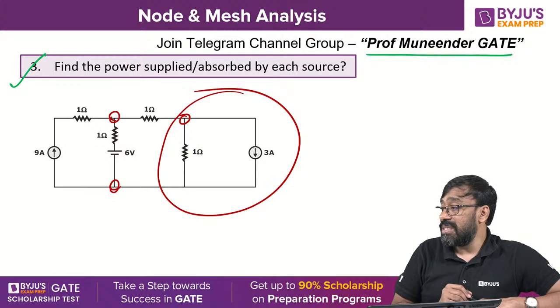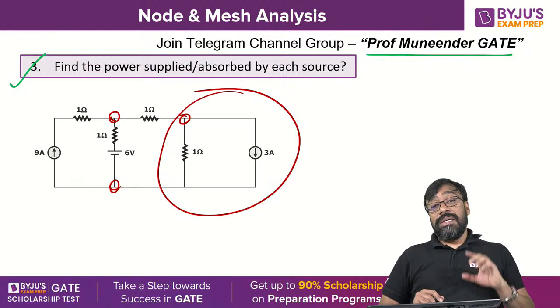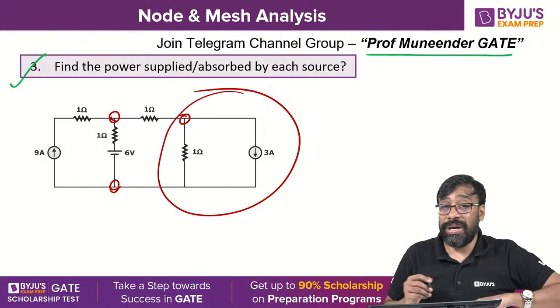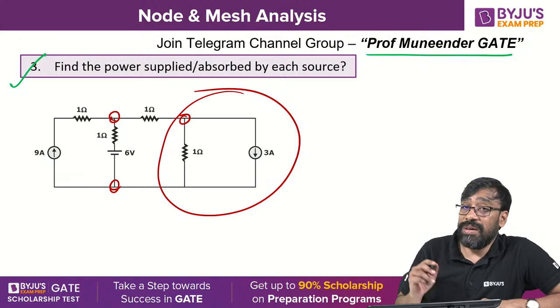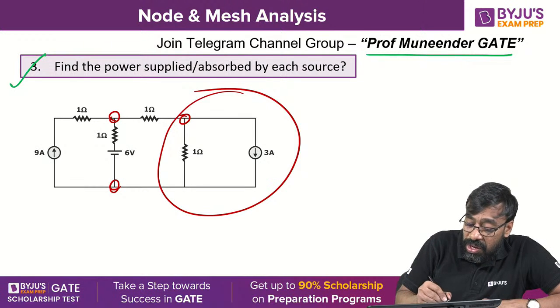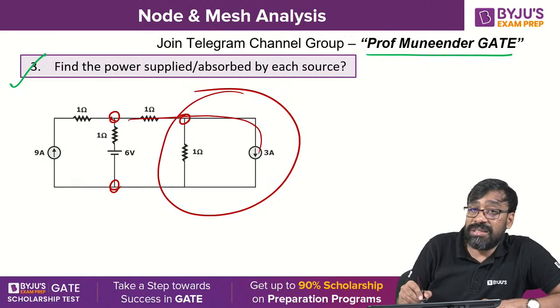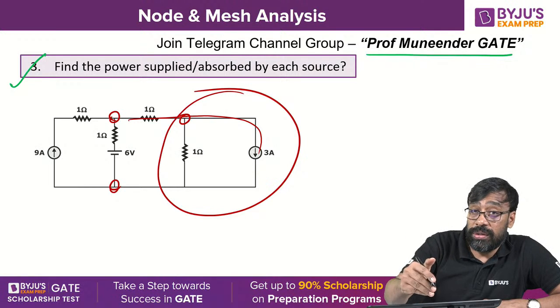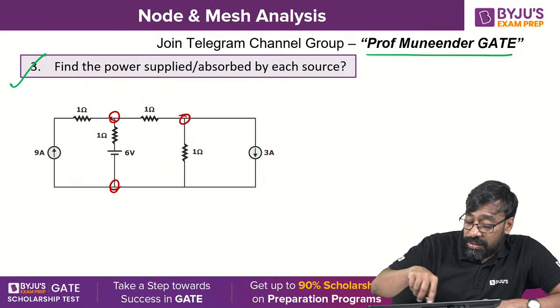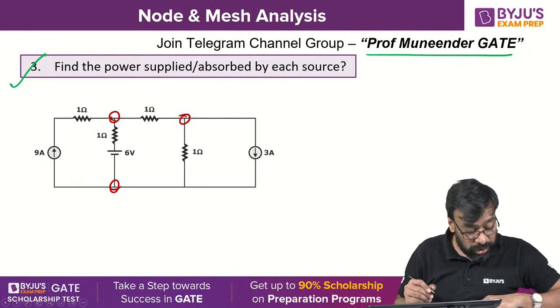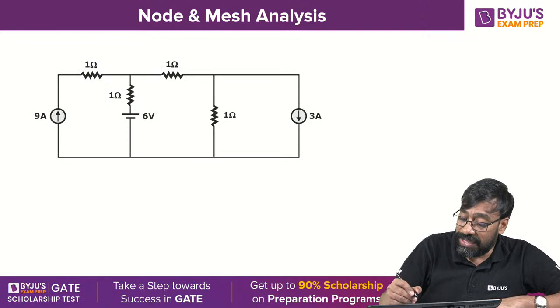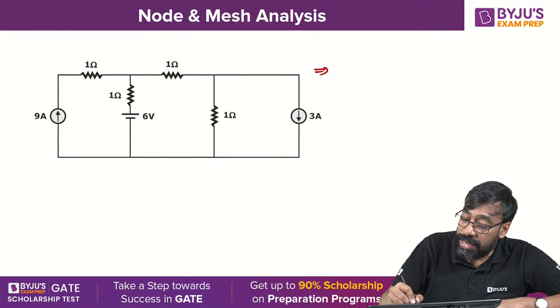A current source with a parallel resistor can be transformed into a voltage source with a series resistor. Once the voltage source with a series resistor is formed, all these elements will become series. Therefore, there is no need to put any node. You understand, all of you? Okay? Yeah, look at this now. I'm going to solve it by applying the source transformation.